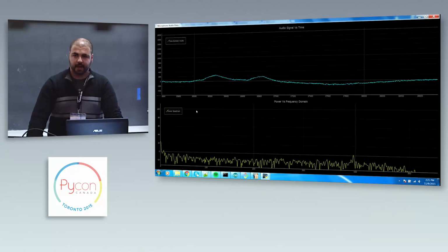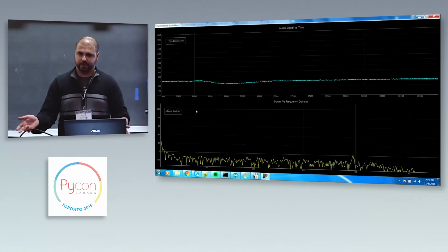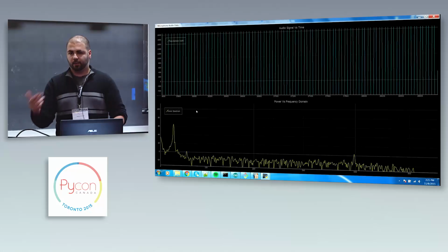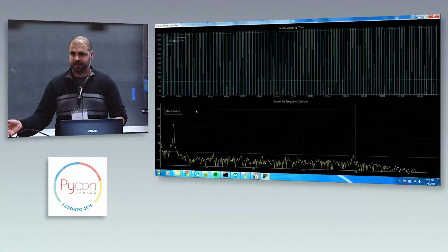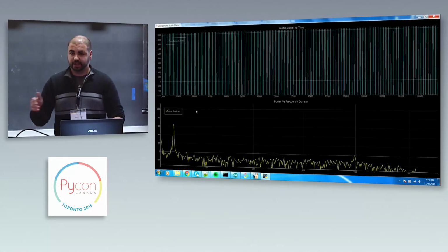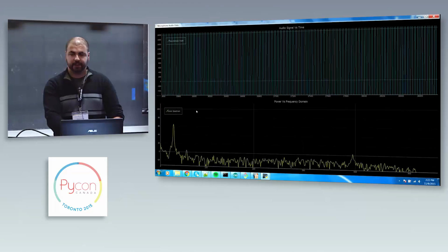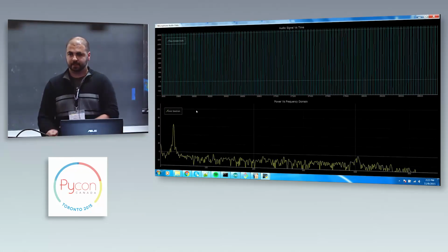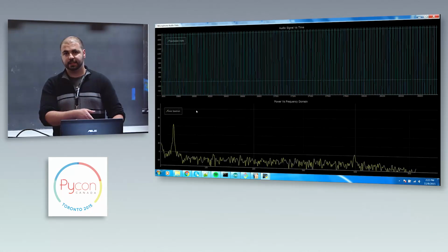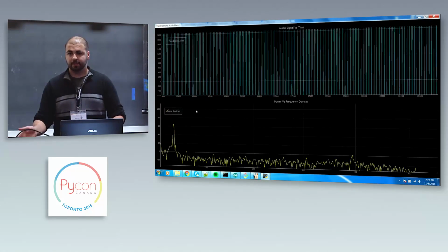The sampling rate is how many samples that your ADC can actually read per second. So if you read, let's say, 1 megasamples, so that's 1 million samples a second, that means you can only look at 500 kilohertz of frequency. If you inject anything higher than 500 kilohertz, you're going to get that effect, that aliasing. And the way you do anti-aliasing is you put a filter right in front of your ADC to stop anything higher than that specific frequency from getting in. That's the main way to do it, and you do that in hardware.